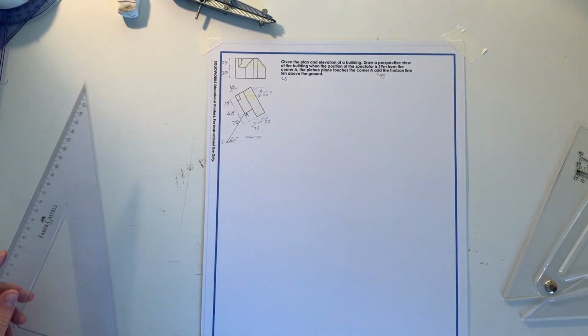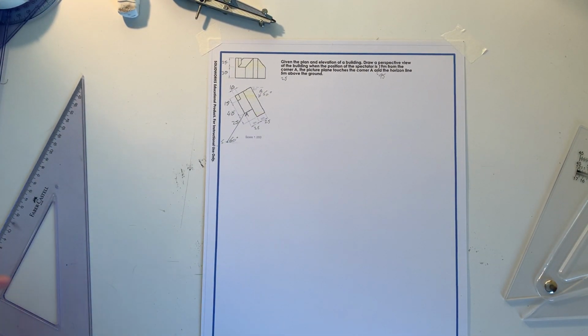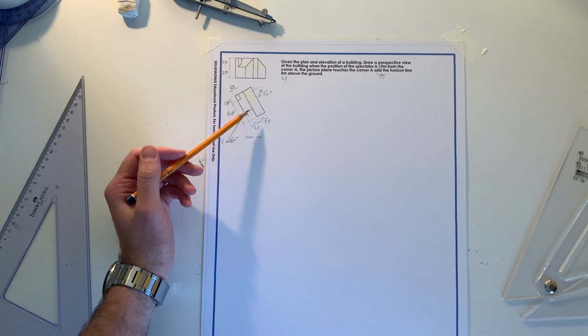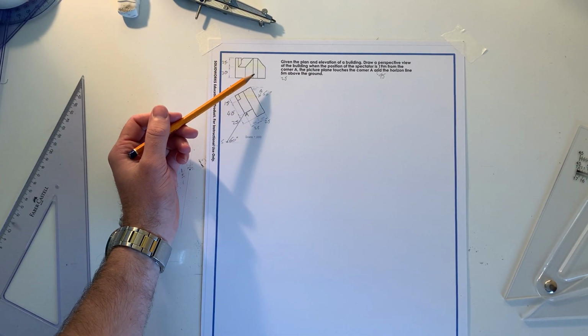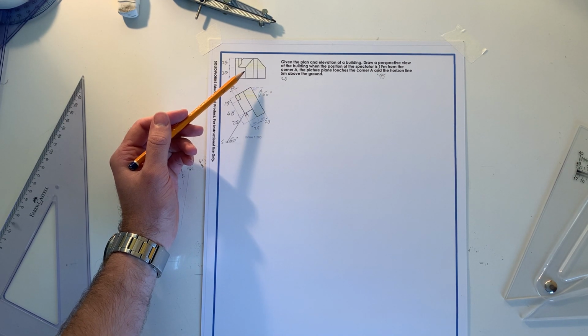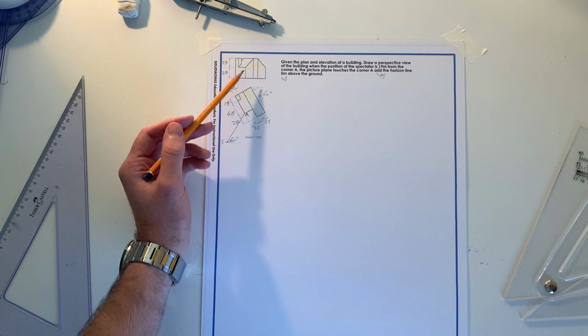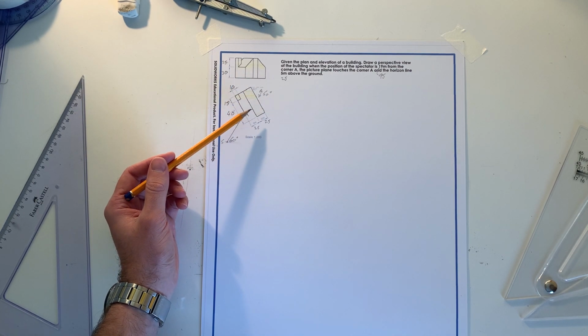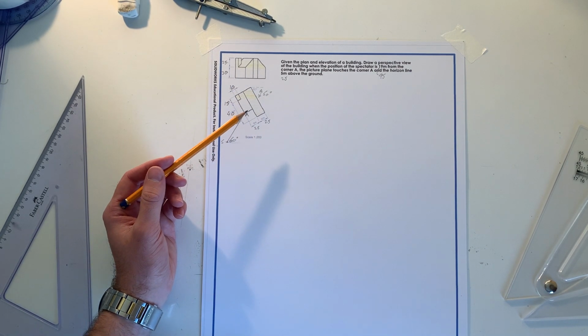Okay, so in this video what we're going to be doing is travelling through an example perspective question. Now this is going to be a 2-point perspective. What we're given here is the question as well as our elevation, our plan of our object. Our elevation is not looking directly in at any particular surface, it's looking in a bit of an angle. But the way that's orientated here is on purpose, so we get a good view of both sides as well as its position over here in plan.